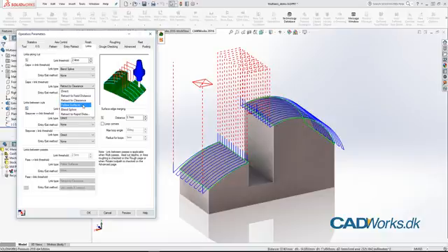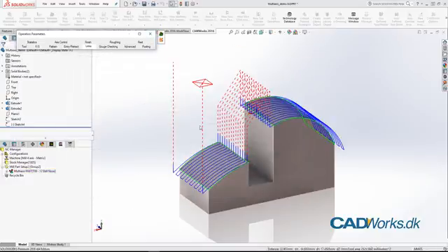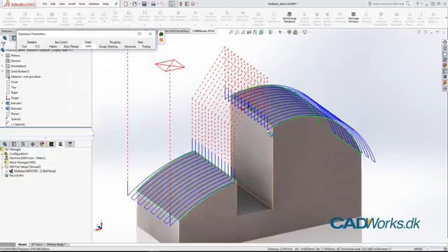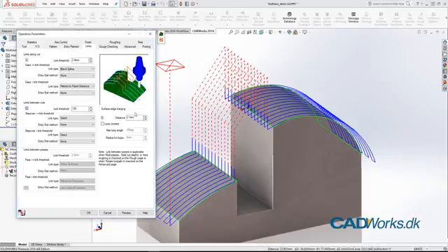If I go follow surfaces, already seen that, it's a direct motion in this case. The blend spline I'm going to wait with for a few seconds, and then I'm going to show you the retract to rapid distance instead. So preview that one, and again, we are coming from the part, and then we feed up 5 millimeters, and then we retract a distance. And I don't recall what that was. So let's have a look.